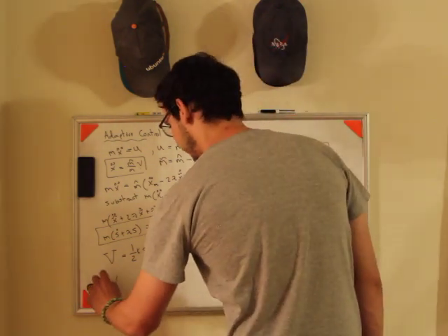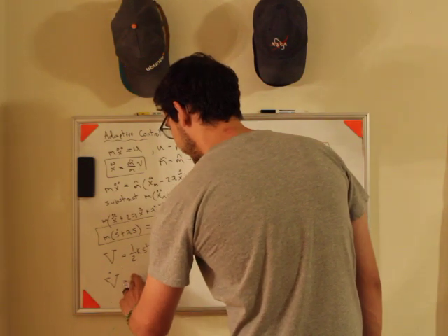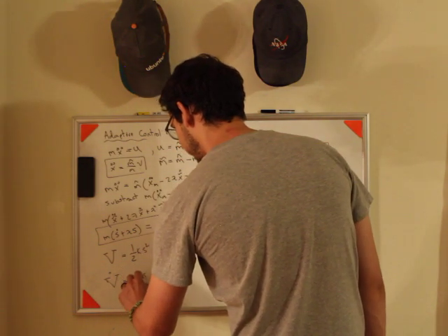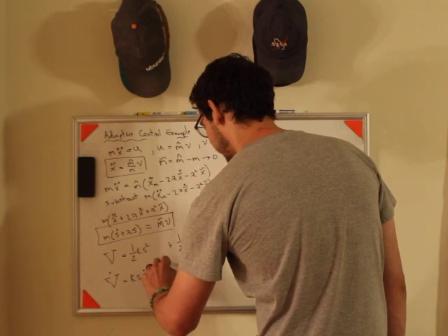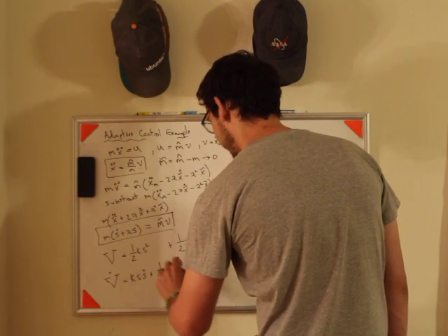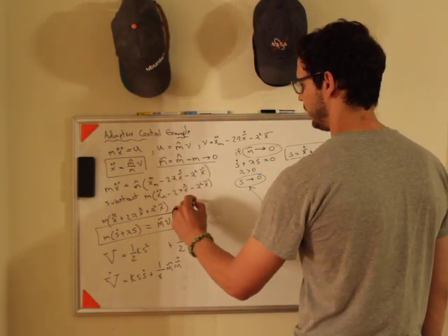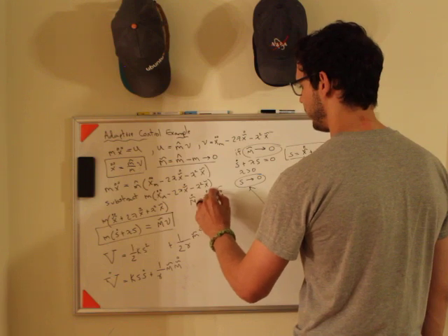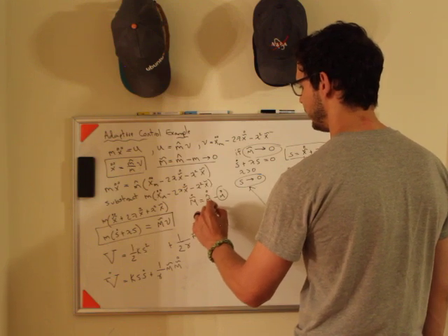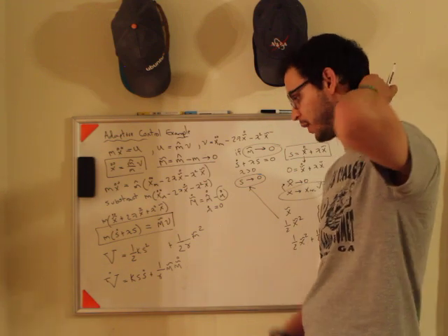So if I take v dot, the 1/2 cancels, and I get ks s dot plus 1 over gamma m tilde m tilde dot. Now let's look at m tilde dot for a second. This is m tilde, which means m tilde dot is m hat dot minus m dot. But I'm assuming that m dot is 0. I'm assuming that mass is constant. If my mass is changing, then this is a completely different problem.